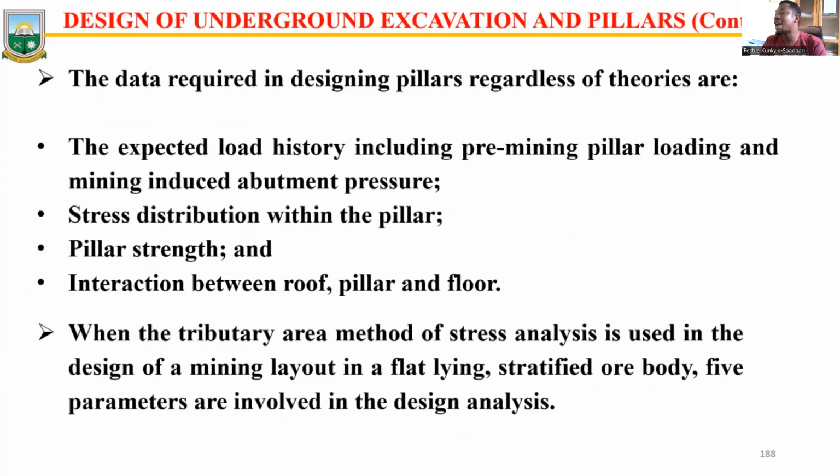So the data required in designing pillars, regardless of theories, are, one, the expected load history, including the pre-mining pillar loading and mining-induced pressure. These are what we require.